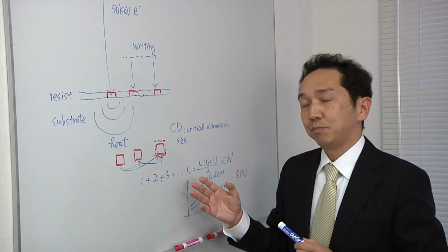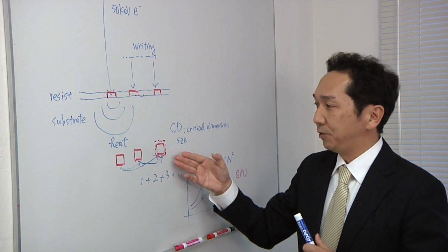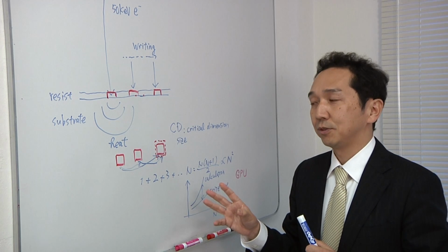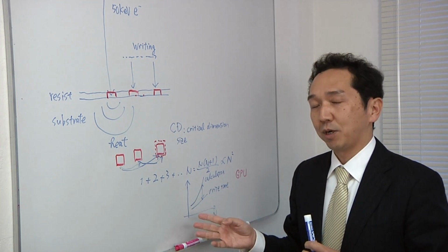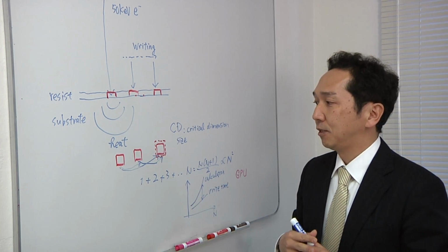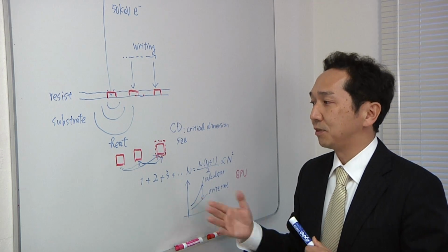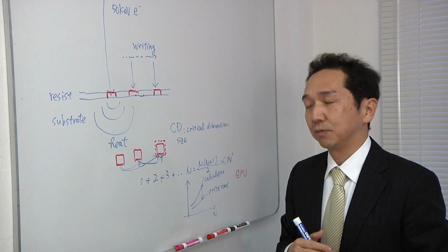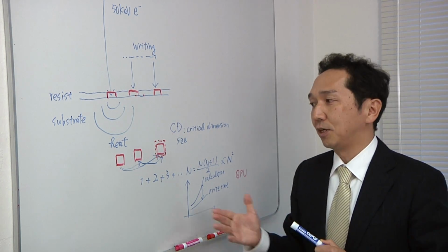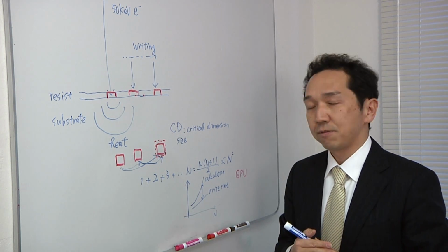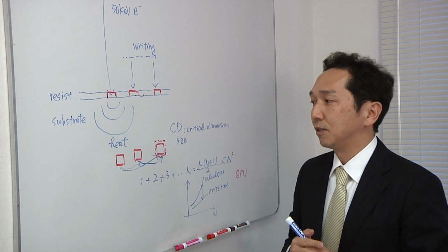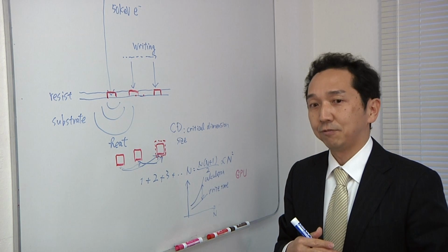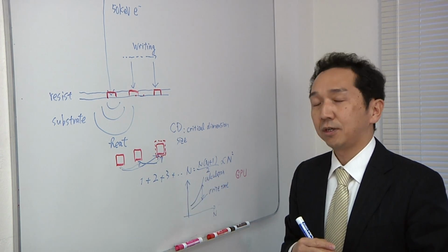What we did in the past to mitigate or reduce this heating effect was to increase the pass count from 2 pass to 4 pass, and sometimes even more aggressively to 8 pass for a nano imprint application. But yes, you're right, it has a throughput impact. And what is desirable is to correct the heating effect by software and hardware.